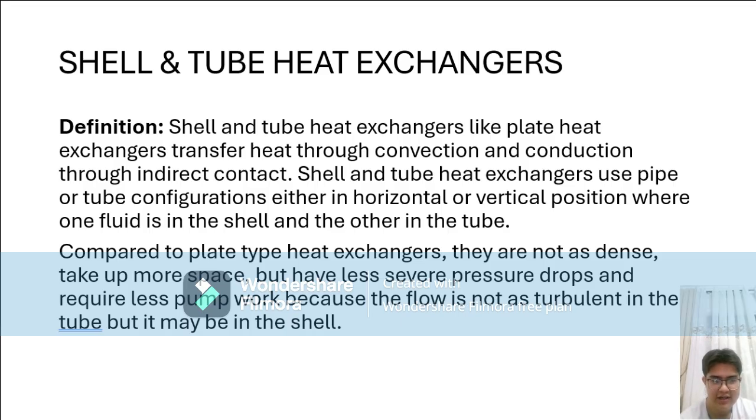Usually the cooling fluid flows up and the heating fluid goes down over the faces of the thin metal plates, and this flow is prevented from mixing by rubber gaskets, so that heating and cooling fluids only flow on their designated odd or even channels.